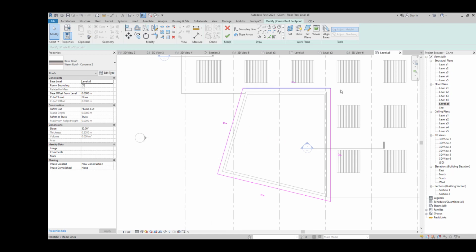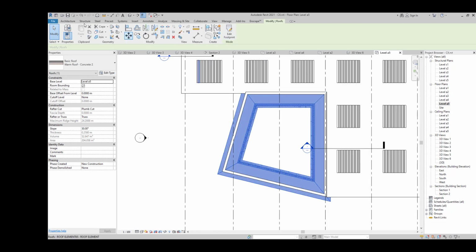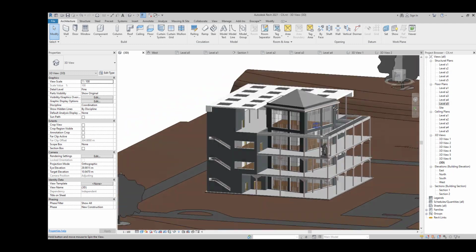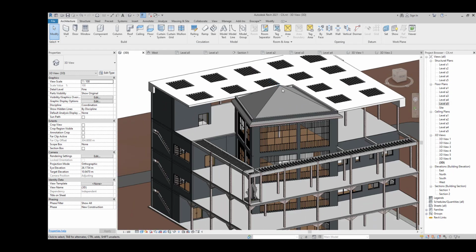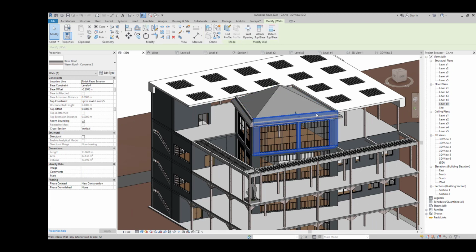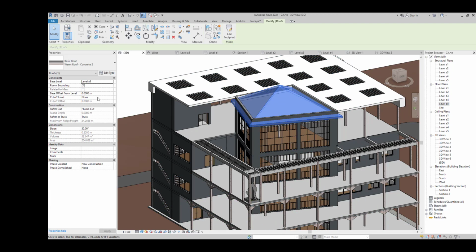And when you're creating your boundary for your roof, you are going to see in dimensions a slope angle. It's changeable. Let's create it first, and after that we will go to our 3D and we will see it's here. So we need to bring it up. Why? Because our wall has an offset by 20 centimeter, so we need a base offset by 20 centimeter.